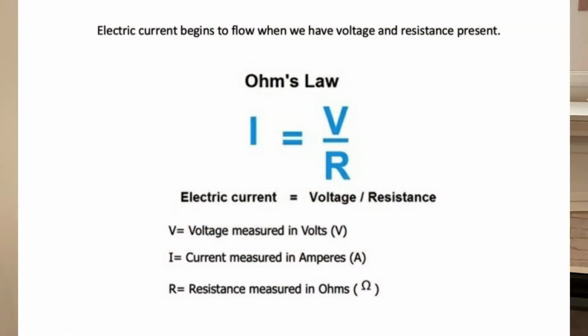And if there's a potential difference between those two ground points, now we have a voltage. We also know that the ground path we're using is not truly zero in its resistance. There's always some little resistance present. So when we have voltage and we have resistance, with basic electrical engineering knowledge, with Ohm's law, this gives the potential for current to flow.